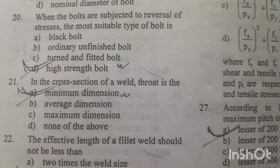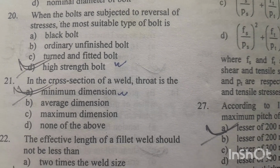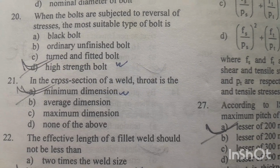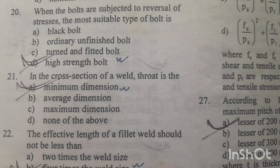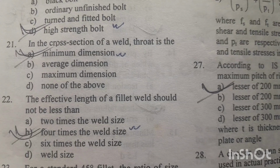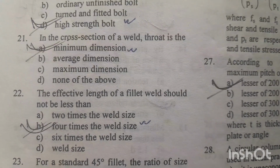Question number 20. When the bolts are subjected to reversal of stresses, the most suitable type of bolt is high strength friction bolt. Option D is right answer. Question number 21. In the cross section of a weld, throat is the minimum dimension. Option A is right answer. Question number 22. The effective length of a fillet weld should not be less than 4 times the weld size. Option B is right answer.